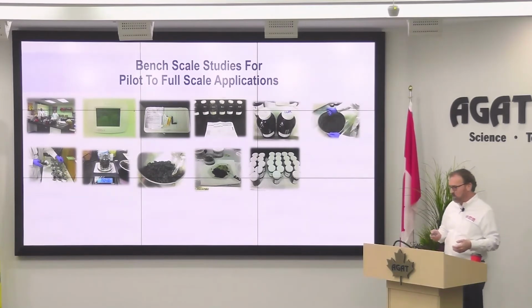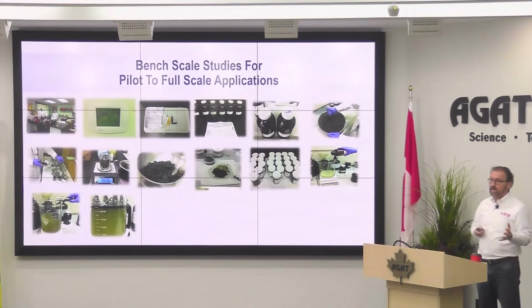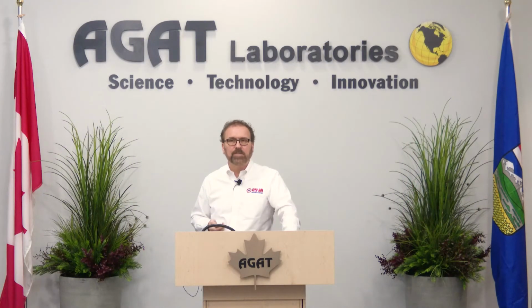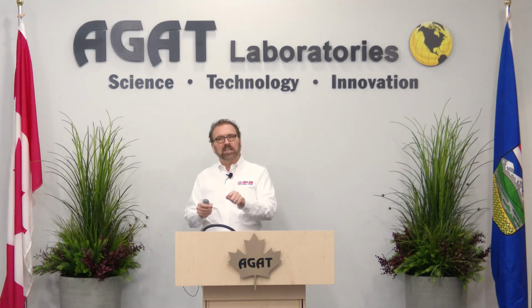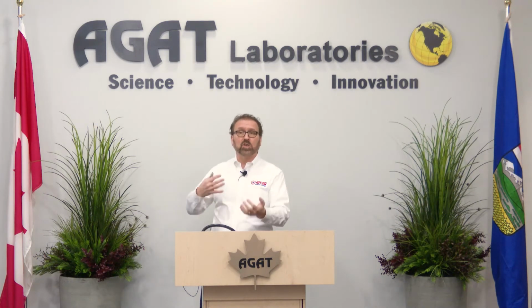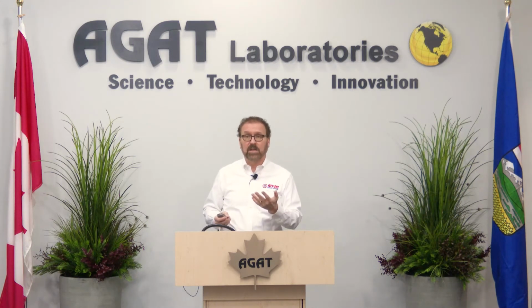Well, the same thing happens with our clients when they give us free phase. In this case, we're actually using their groundwater in a 4-liter beaker. We're using about 2,500 mils of the groundwater, and then we put about 100 mils of free phase on it, and we put a magnetic stir bar on the bottom, but we're only turning at the setting 3 of 10. So it's moving, but not so quickly as to cause, shall we say, turbulent action or stirring. You won't see much movement on the surface at all of this liquid.